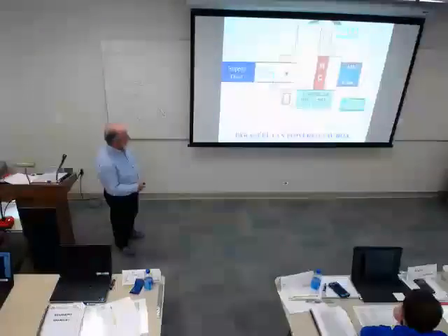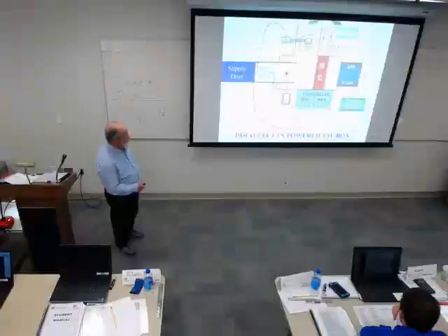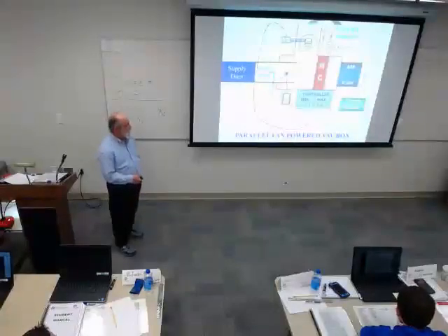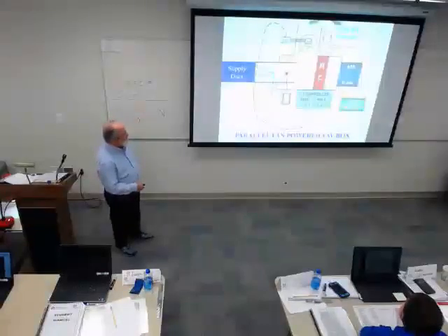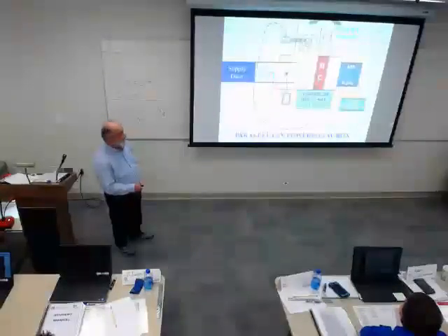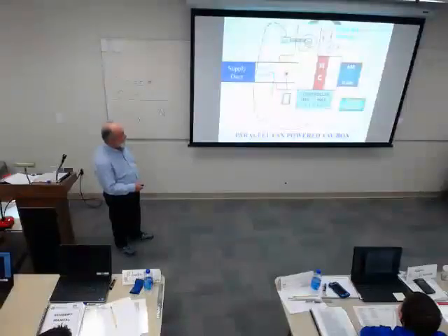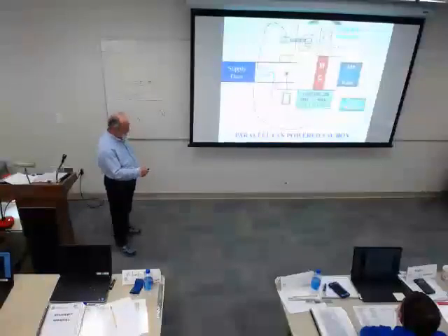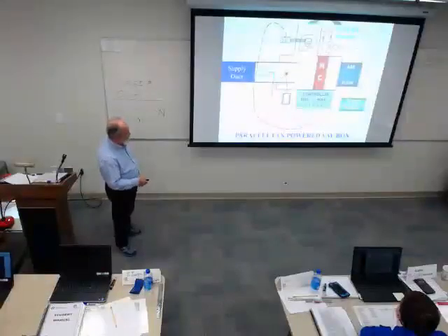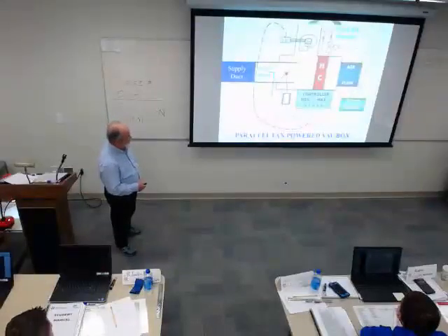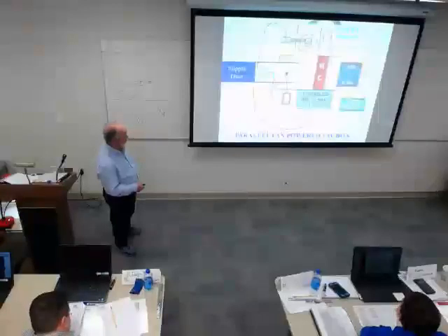Here's one that I like to see a little bit better because the fan's out of the airstream. The one I like even better than that, the heating coil is there by the fan, but that's another story. But this is another one. That fan runs when it's necessary and doesn't when it's not. And when it's required to heat, the fan will bring in air from the plenum essentially, as you see there, and will run up through the heating coil. You may or may not have that damper open there. Those are really good for, like the others, for night setback.